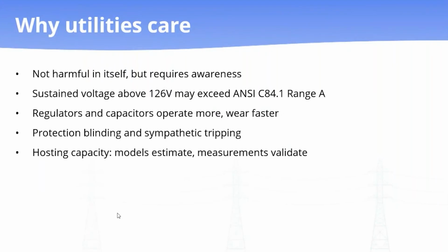The impedance that produced voltage drop on the way out, conductor, service drop, transformer, produces voltage rise when you reverse the current through it. It matters more here than on transmission because feeder resistance is significant, so real power export alone moves voltage noticeably. The field pattern is consistent. Solar climbs, net real power falls through zero, service voltage rises over the same window, and the day's highest voltage tends to line up with its deepest export.